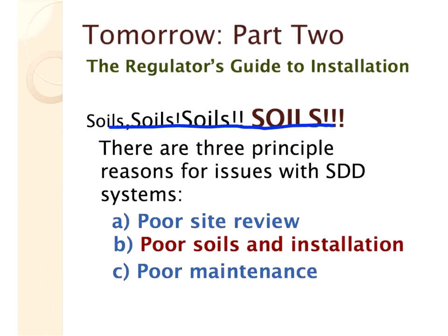But with the soils, you can improve the treatment even if necessary. Let's say you started with septic tank effluent. Let's take that system we had 2 slides before, which is septic tank effluent. Well, in this case, if there is a soils error, you could put in secondary treatment and that might save it. But if you've made a real design error with soils and you're already in secondary treatment, boy, you're in trouble. So that's why I stress that the most important thing you can look at is the soil study.